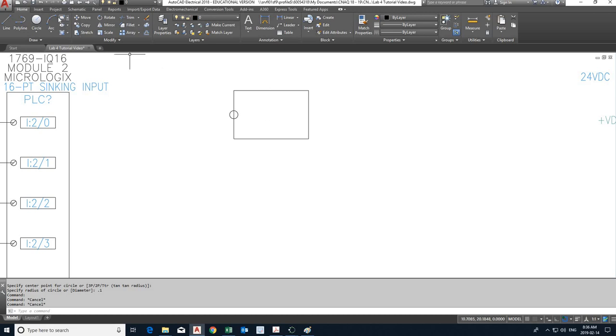Click, well, you issue the rectangle command. Click anywhere and then at 1.8, comma, 1.2. Enter. And make sure it's placed at layer 0. Now, I have 2 terminals.